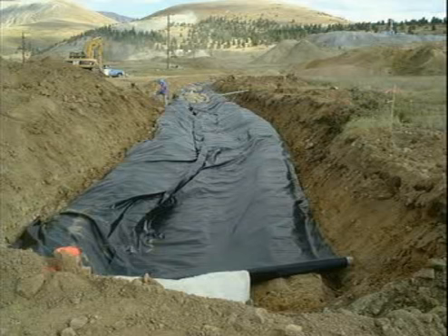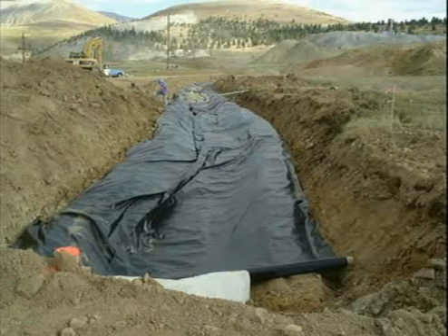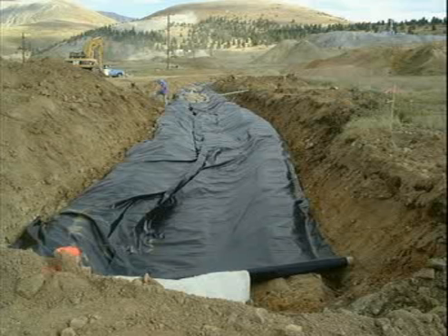Now above that black mesh, you can place either rock or the jute mat, or maybe even concrete. Now these ditches, they're not rocket science. They can go in fairly fast. They can be fairly low maintenance. But the main thing about them is that they have to pass the design event. They ought to be able to withstand erosion from the much larger events. So back to you, Jim.